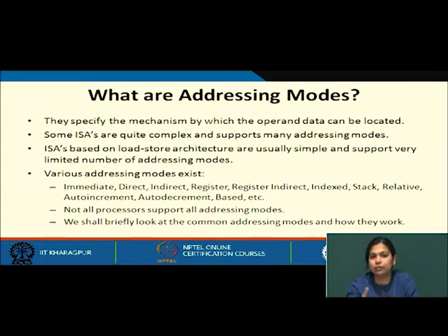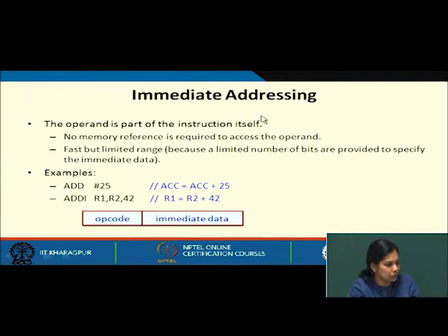This is the class of addressing modes that exist in all the architectures, but different architectures have a different set of addressing modes. So, we shall first look into some common addressing modes and how they work. Coming to immediate addressing mode, here the operand is a part of the instruction itself. So, you need not go anywhere to get the operand, rather your operand is a part of your instruction. Here no memory access is required to get the operand,